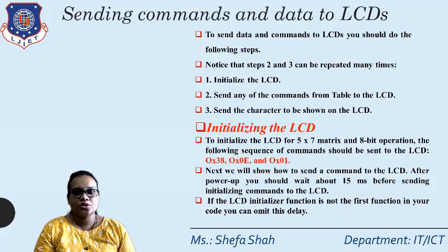to clear the display. Then to start to write the characters, we need to write display on cursor blinking. Then for transferring the 8-bit data, we need to write the code, that is 38 in hexadecimal, to the LCD. So these are the various commands which we will use before sending the character to the LCD.